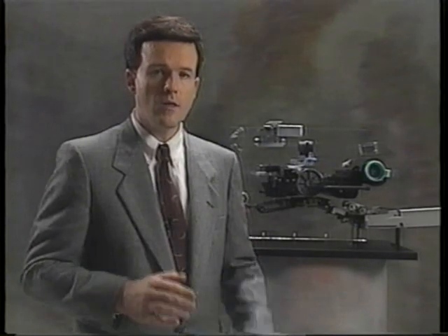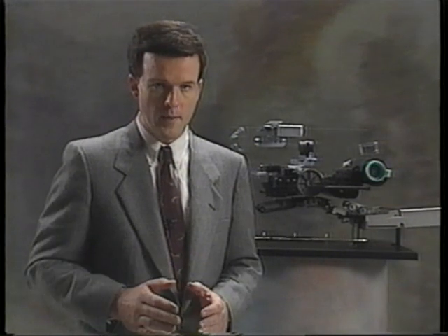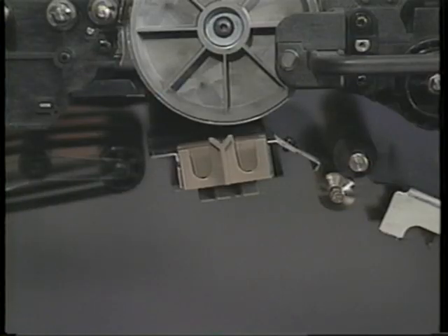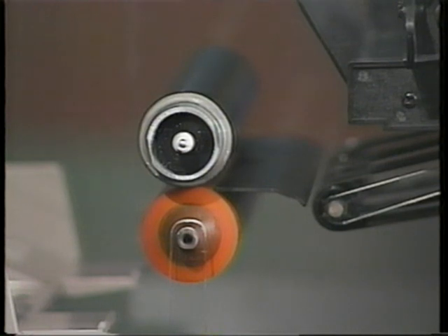At this point, the original image is on the paper, but it's held in place only by a relatively weak electrical charge. To turn this into a usable, permanent copy, the toner must be fixed in place on the paper. That happens right here in the fusing system. After separation, the paper moves away from the drum over to this point, where it passes between two rollers.